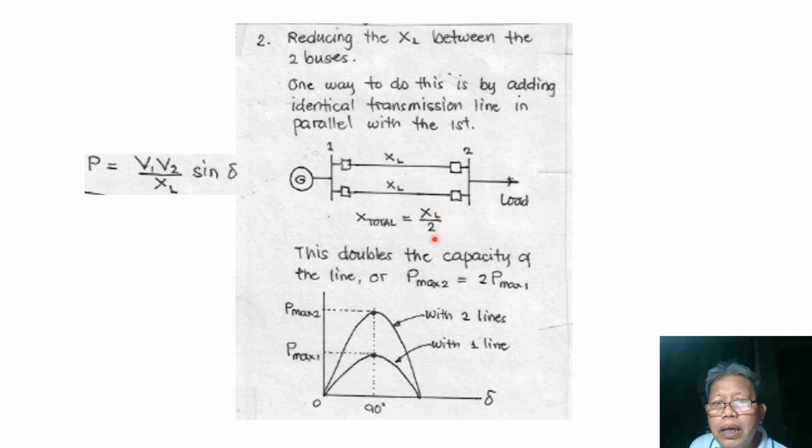So making D sub S large means we have to increase the diameter or radius of the conductor in order that its inductance would be reduced. So that is one way of reducing the inductance of the line, making use of larger conductors.